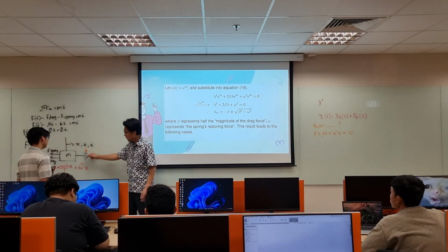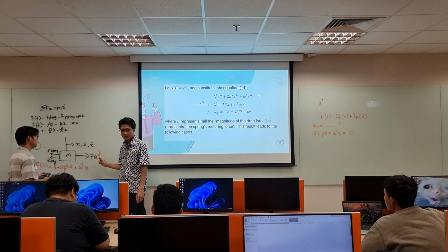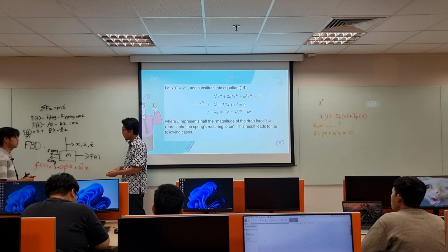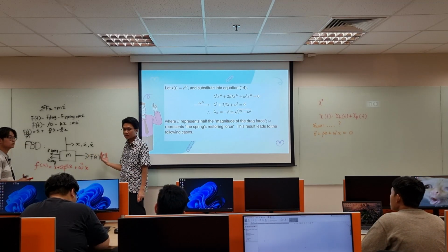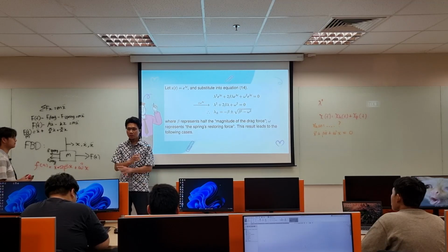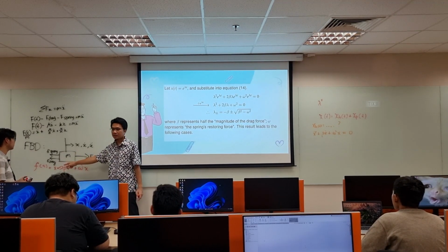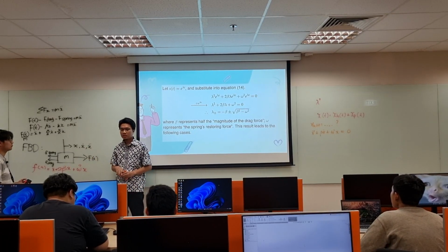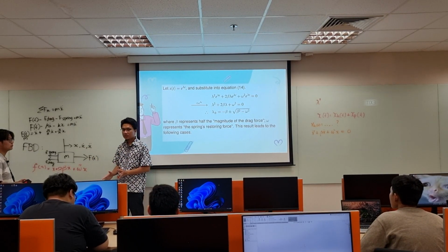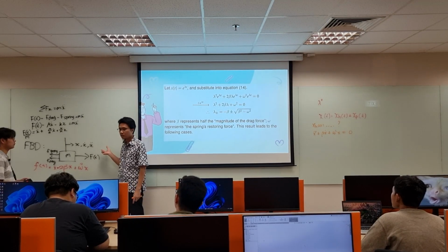But when you have a force like this continuously giving a sinusoid or a periodic function, the homogeneous solution will always die out when you have damping, or when you have the drag. So in steady state condition, what you will see is the particular solution only.